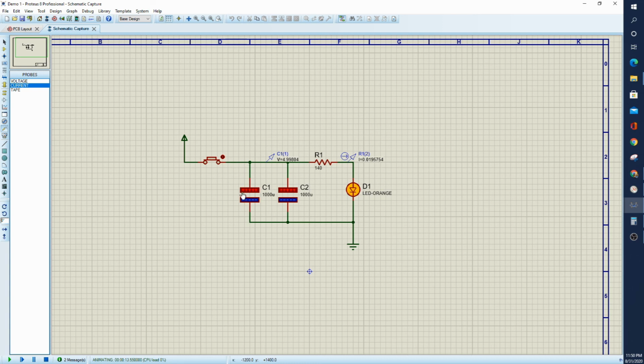And now we can see that our capacitor C1 and capacitor C2 are fully charged. And we're sitting just 2 millivolts below peak. And that's because there is a little bit of resistance here in our button. And we're drawing pretty close to 20 milliamps. We're 400 microamps too low. And so that's good enough.